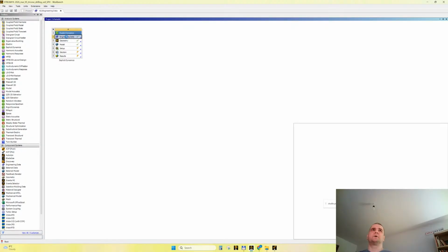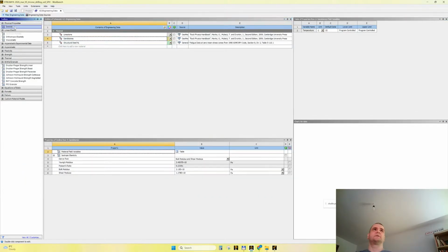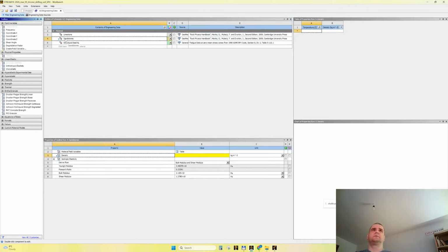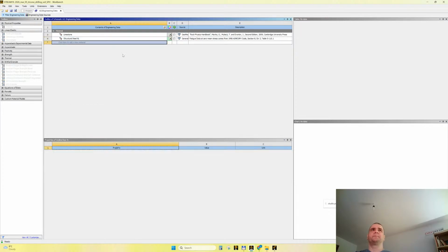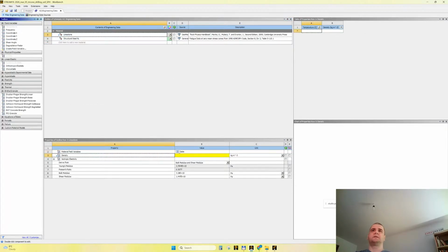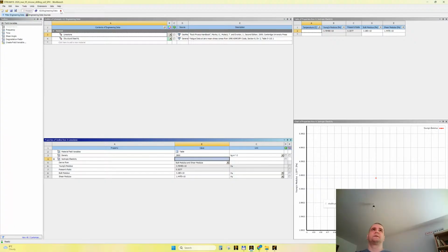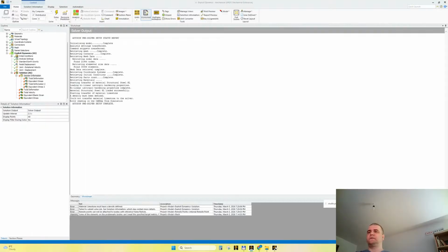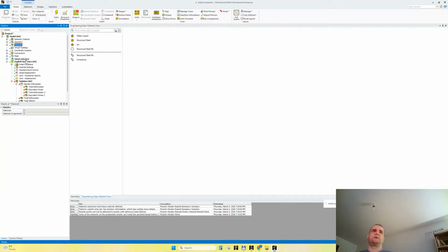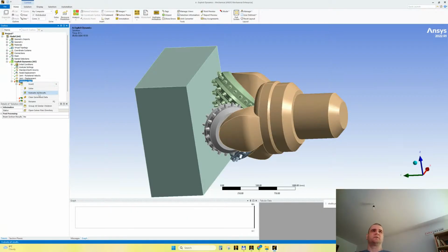This is what I will give. Okay, so density, double click, 2800 from my side. Save, go here, right click materials, refresh materials. Right click solution, clear generated data, yes, save. And solve.